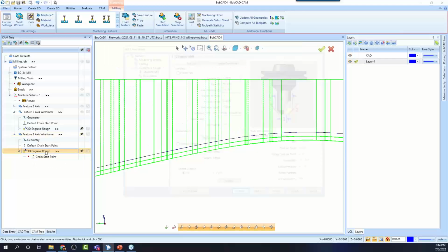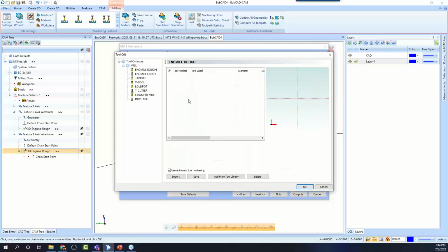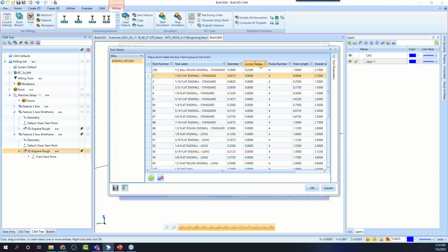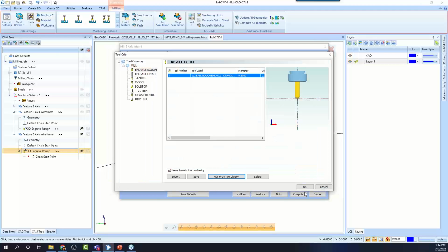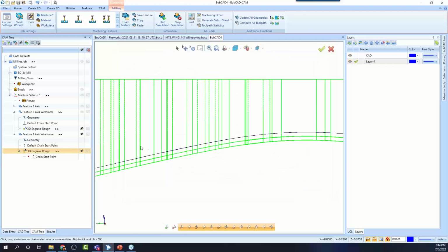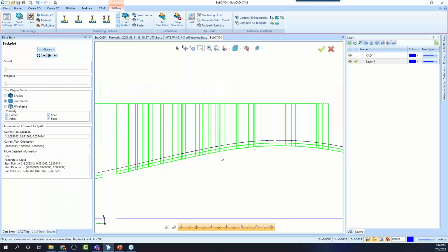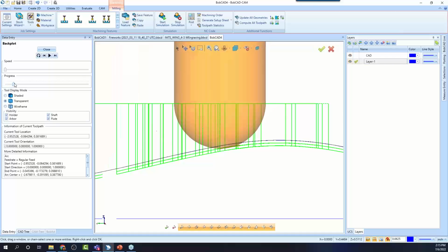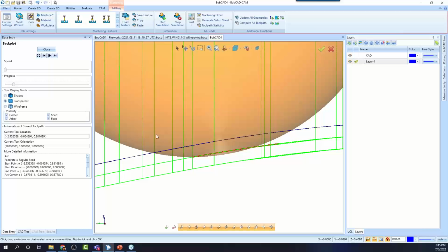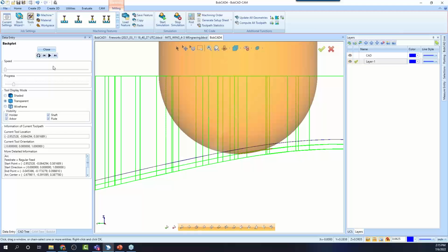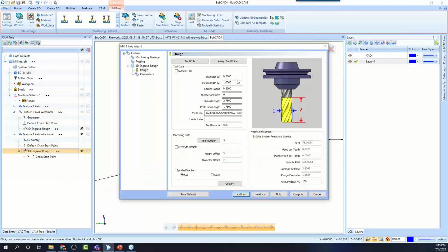If you're going to do this, maybe instead of a chamfer tool, maybe just going with a good old ball mill might be a good way to go. A smaller ball mill. I just need corner radius. All right, well, we'll go with a larger one to begin with. Okay, again, to exemplify how the center, or in this case, the tip of this tool is driving to that. So look at all this area, all these different sides of the tool that it would be colliding, because 3D Engrave has no compensation. We can kind of drop our